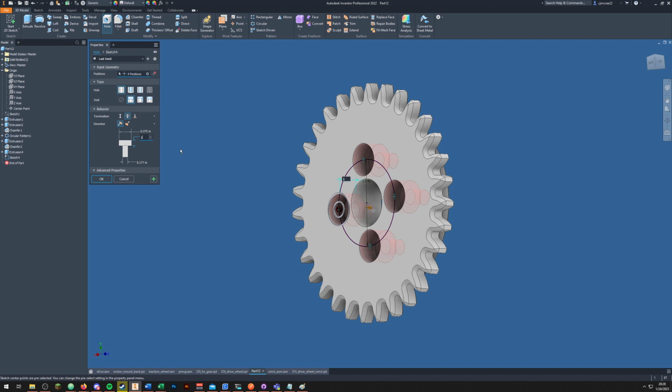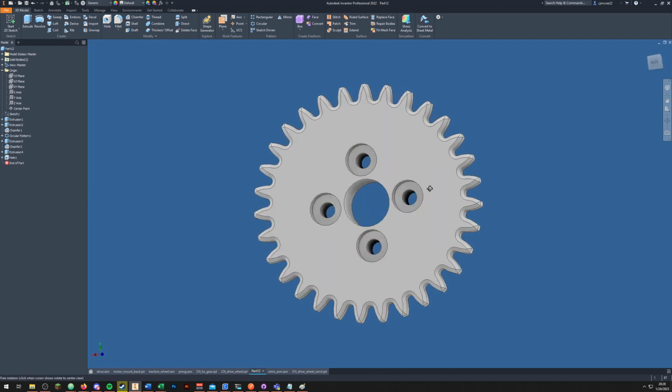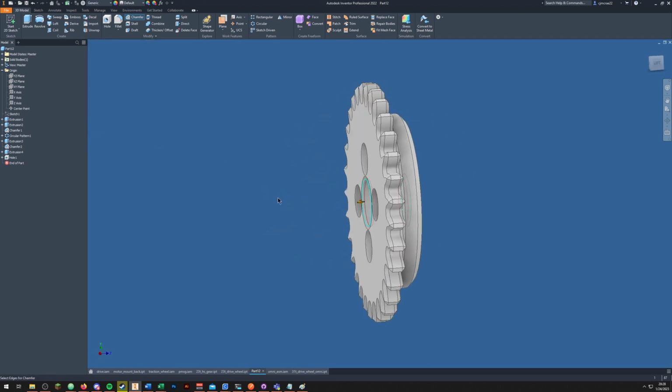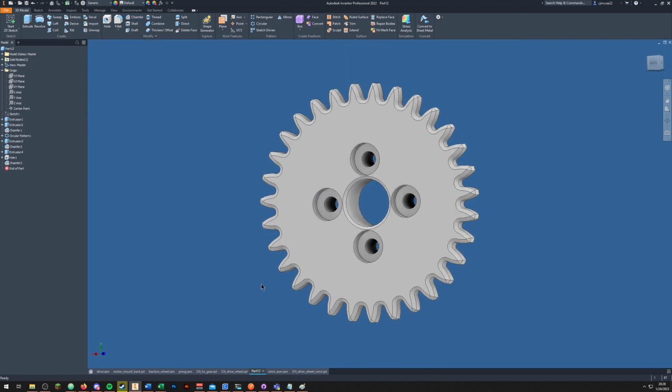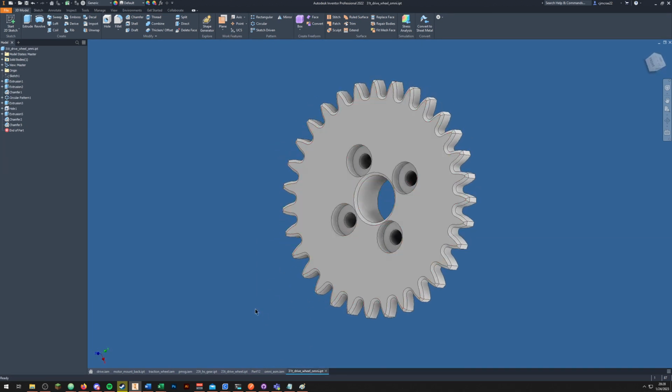We're going to countersink these by 1/8, not an 18th, an 8th. 0.375 diameter counter bore, and then 0.177 is what I use for the actual screw diameter. Click OK, and then one final chamfer. We'll go with 32nd on those two surfaces. And so now we have, oops, I won't save that. Now we have this, which is almost effectively identical to what I've designed here.